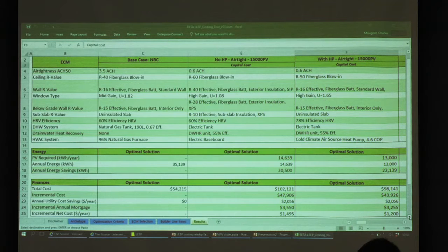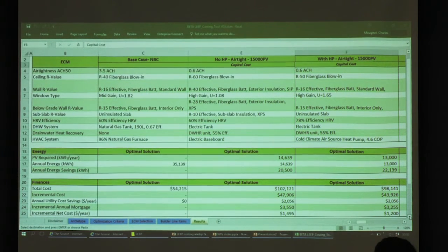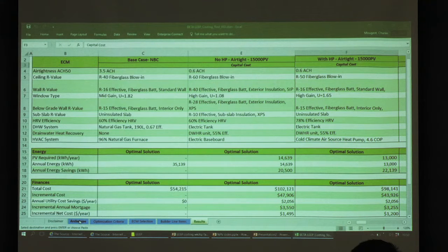Some of the new heat pumps that are coming out now, like the 21 SEER, the variable frequency drives, they do resolve a lot of those issues on one-stage or two-stage heat pumps. They do cost a lot more, obviously, but paired now with an ECM drive air handler, you can really see some amazing efficiencies, and they actually do provide a good amount of heat now too. So there's big advancements, but again, the cost is slightly prohibitive still right now. It's coming down.